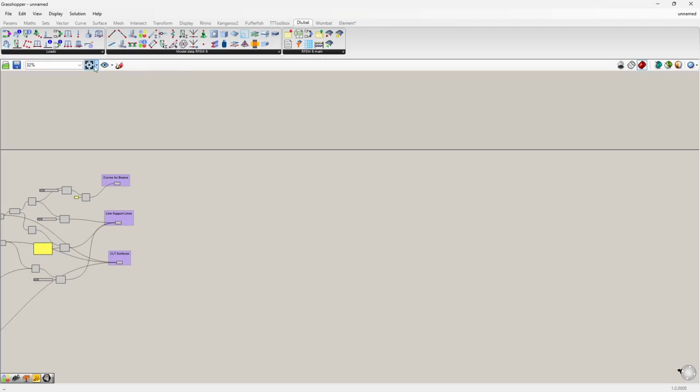We have another group which is called loads. In here you have components to create load cases, load combinations, but also the loads: nodal loads, line loads, member loads, surface loads, but also imperfections, in case you want to assign them as well. And the last group contains general components, for example, the export component, the import component, a component that allows you to run the calculation of RFEM 6 via Grasshopper, or other components. For example, as I said, I use in an internal version the global mesh setting component.